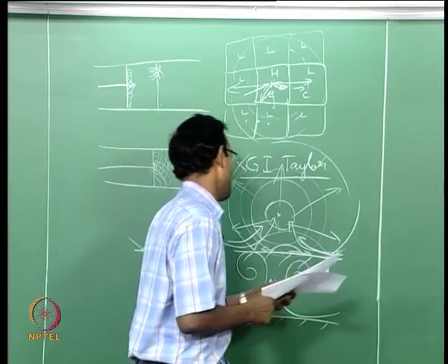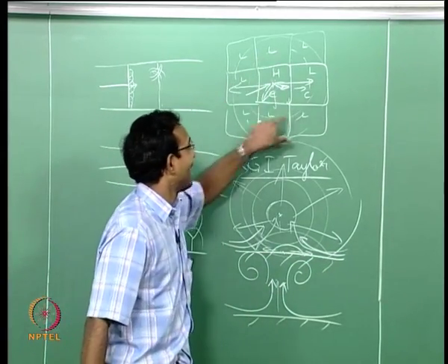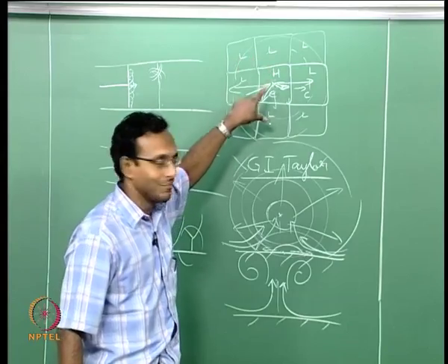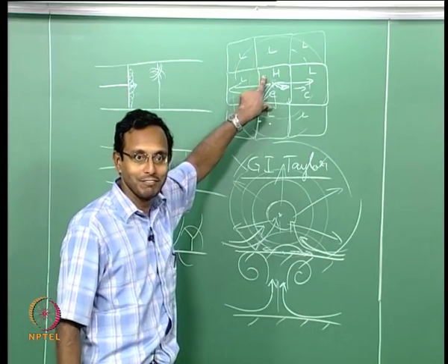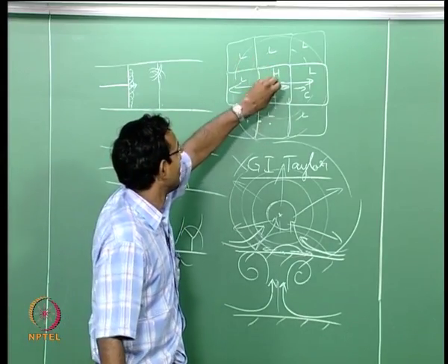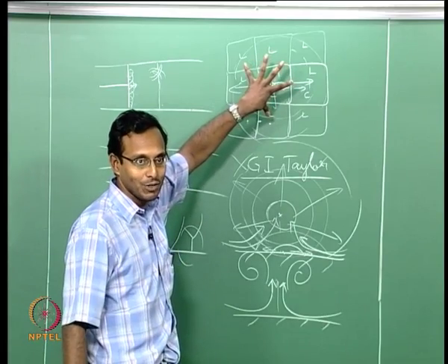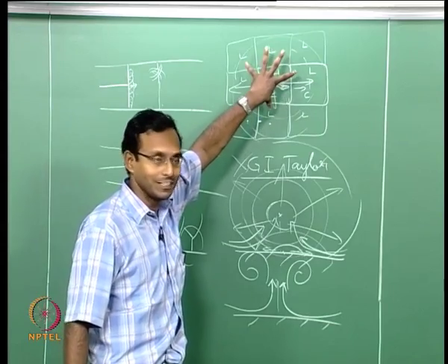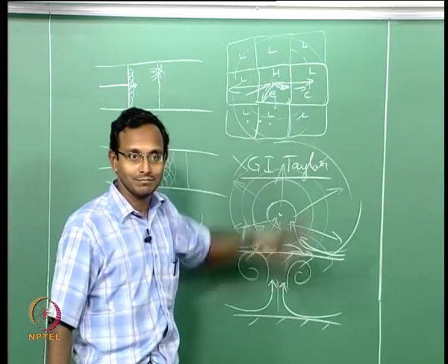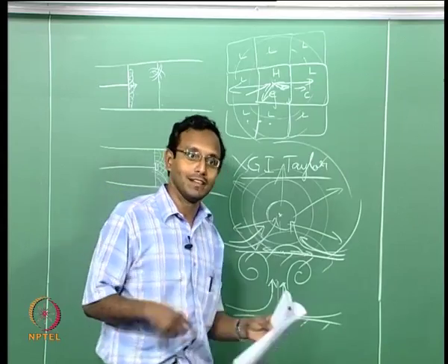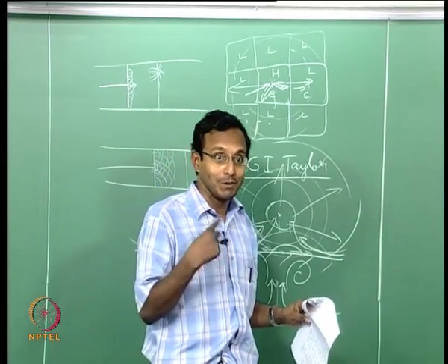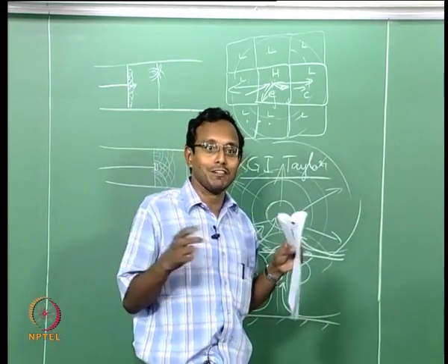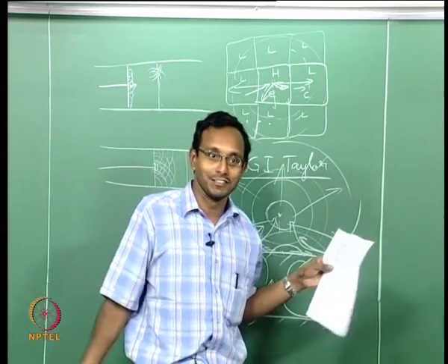But anyway, this is what will happen if I think about unsteady flows where there is one point alone having very high pressure. This will send compression waves out, expansions go in, and then the expansions go out. After that they come, bounce off and go out again. All this will happen in unsteady flows. This will keep on happening multiple times till you come to a point where those waves are very weak.